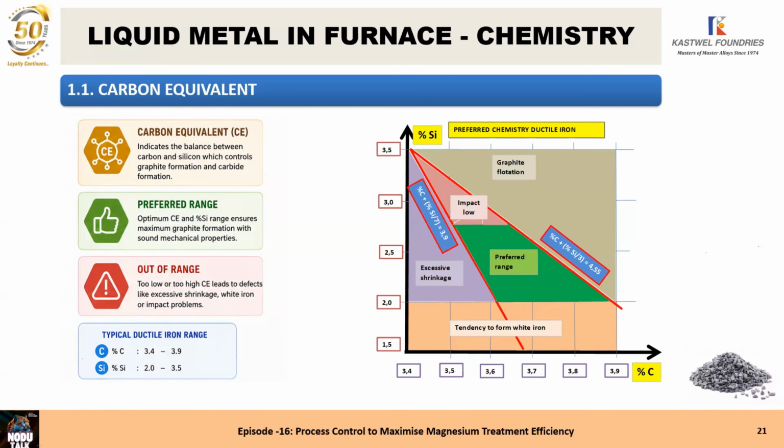There is no point in increasing the temperature of the metal in the furnace just to compensate for the temperature losses. You should reduce the temperature losses as much as possible and increase the rate of transporting the metal, pouring the metal, covering the metal, and the deslagging process. Avoid the losses as much as possible instead of increasing the metal temperature to compensate for them. This is my comment, staff.